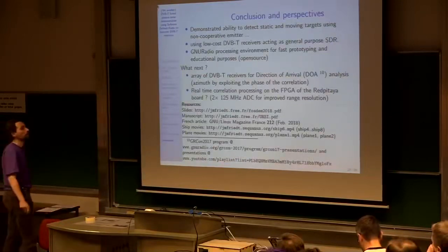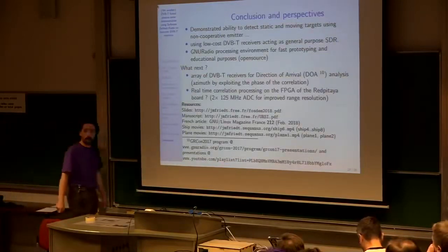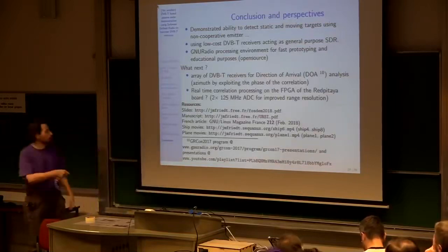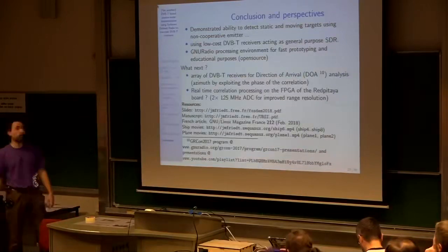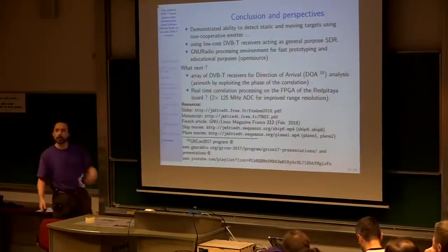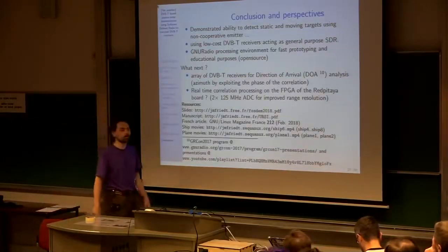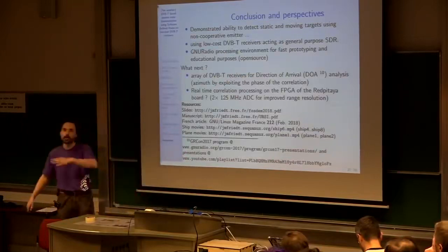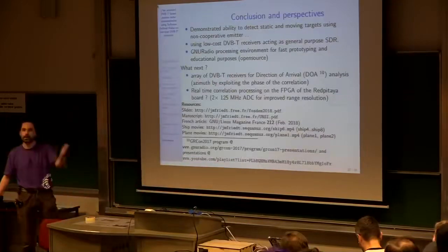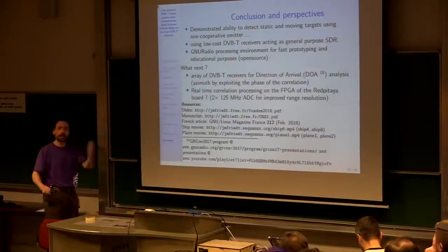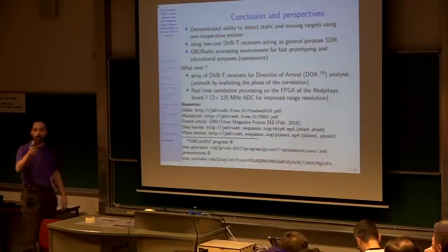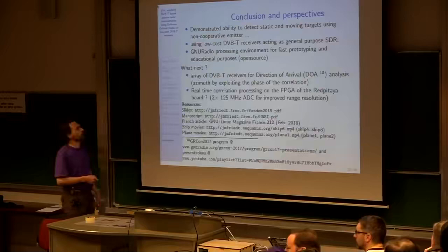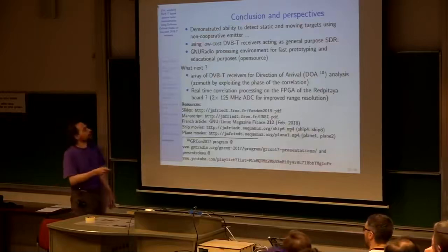And what we would like to do this summer is to investigate DVB-T arrays, and if we want to do direction of arrival, which seems to be the hot topic if you look at all the GRCon presentations, well, direction of arrival needs phase synchronization. At the moment, I don't have phase synchronization. I'm looking at a strategy similar to a Dicke switch, where you're periodically switching your DVB-T receivers onto a reference signal to analyze the phase offset. So I have the hardware in my backpack if anyone is interested. That would be the work for this summer, when the weather becomes a bit better: direction of arrival.